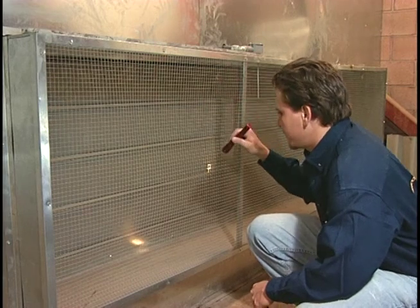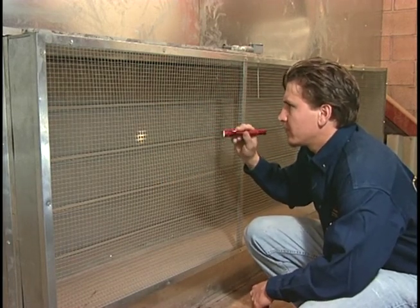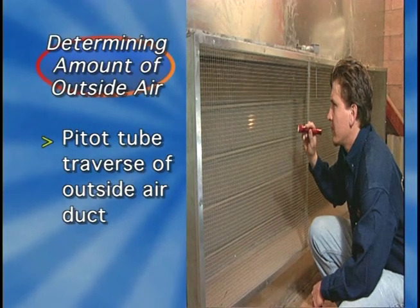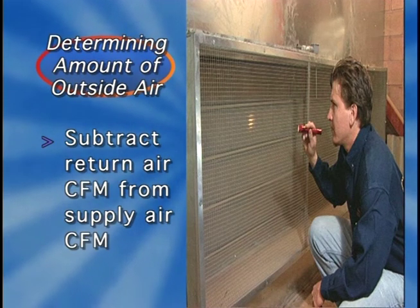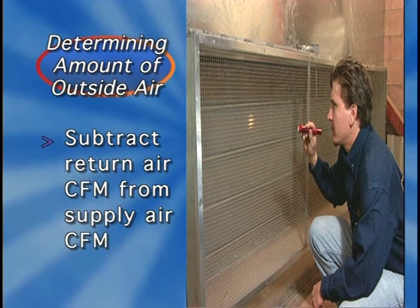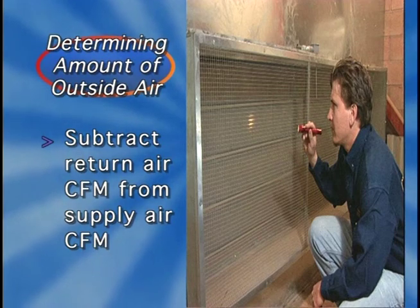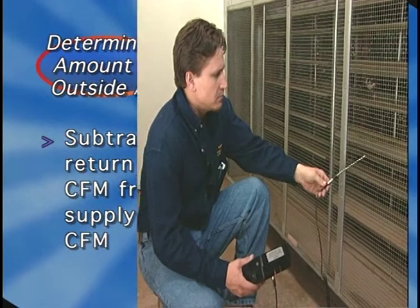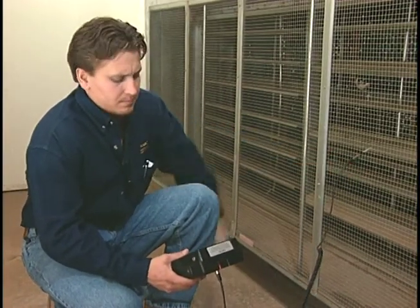To set minimum outside air, the technician first must determine the actual amount of outside air. One way to do this is with a pitot tube traverse of the outside air duct. Another method is to subtract the actual return air CFM from the actual supply air CFM. Supply air, of course, is equal to the return air plus outside air. However, if neither of these methods is satisfactory, the temperature method may be used where practical.